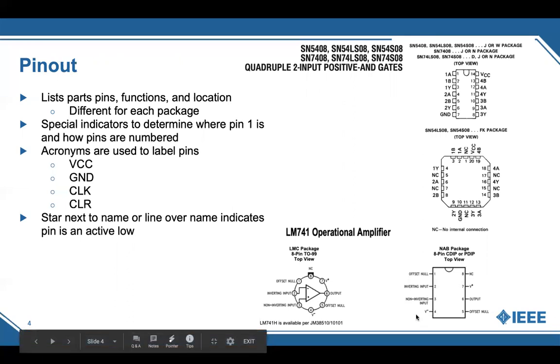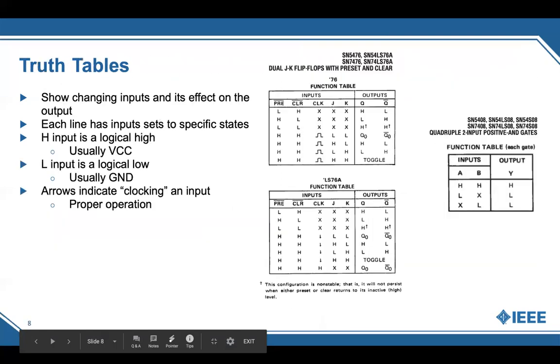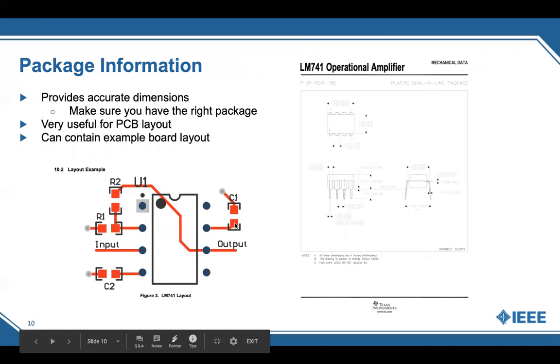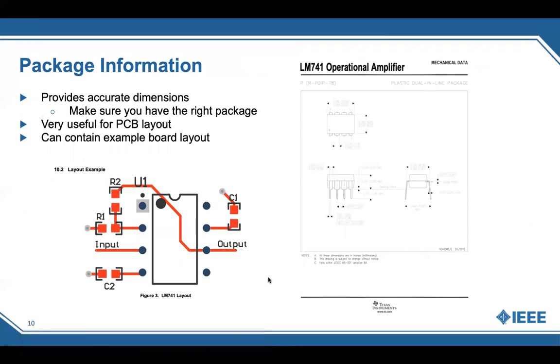are the plus and minus 15 volts to get your operational amplifier to turn on. And then pin 5 is another offset null. So that's how these connections show. You have capacitors going in for plus and minus 15 volts just to slow down that current. And like I said, R2 serves as your feedback resistor for your output, and R1 serves as your inverting input resistor, and right here we just have no resistor.